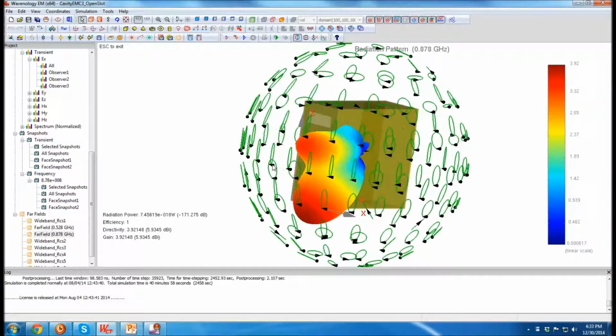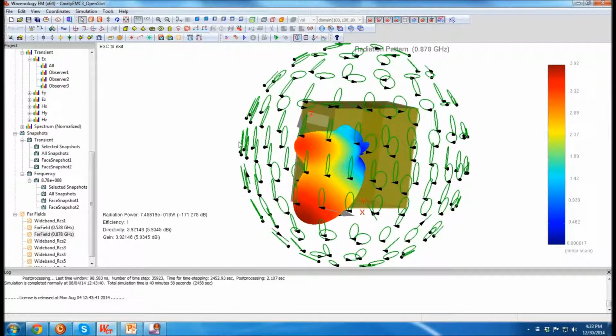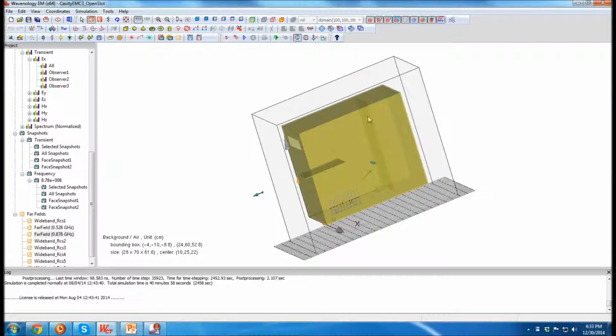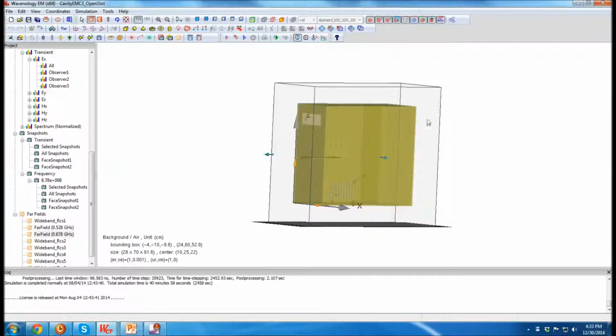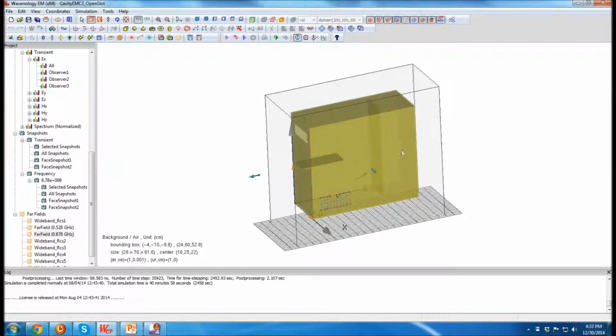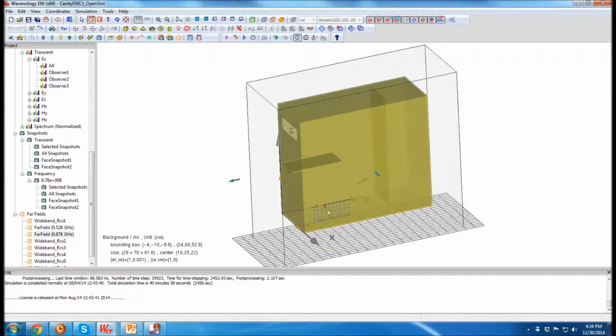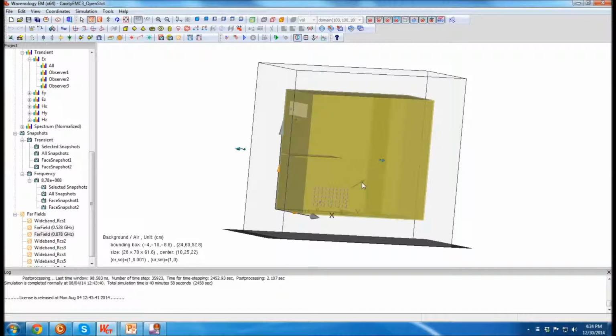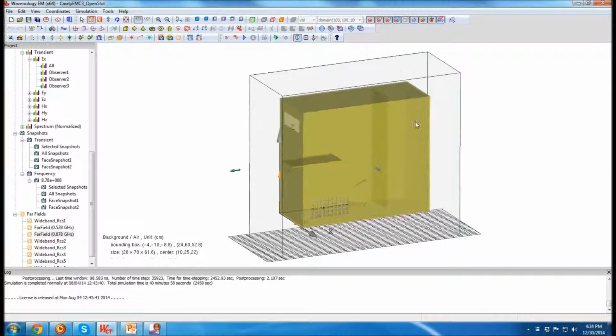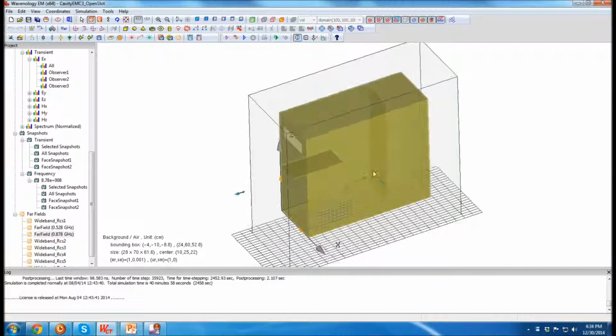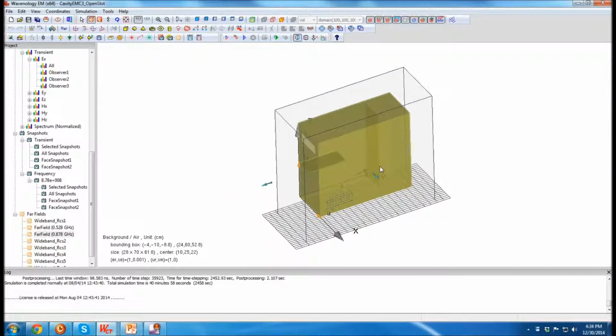Okay, so that's how we analyze by adding in the internal structures. How does it change the resonant frequency? By adding in the small window, it doesn't bring much radiation. It's pretty safe to add small windows, but if you have big slots, especially when they are comparable to the wavelength of your excited pulse, then it really needs concern when you're trying to make some EMC solutions.